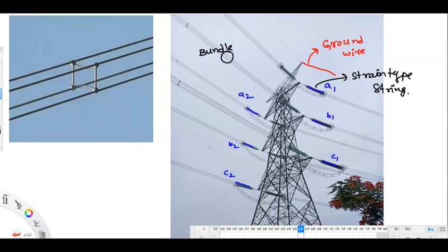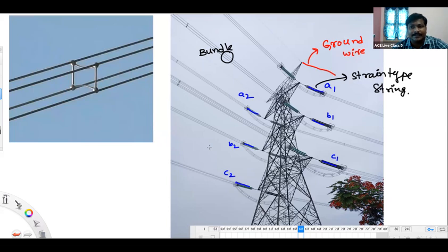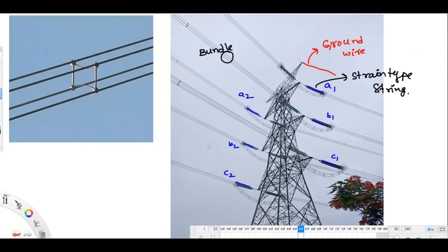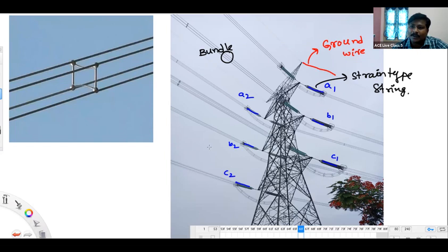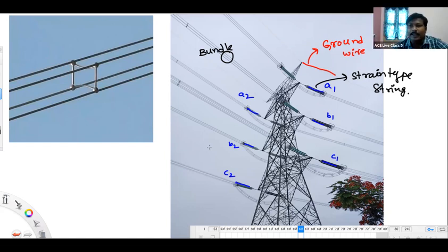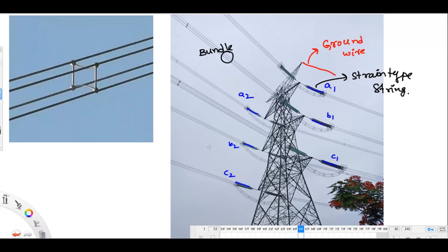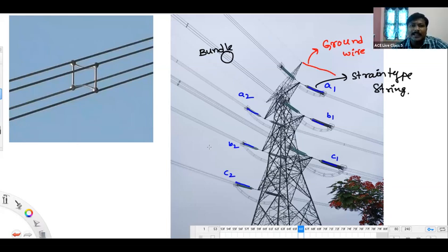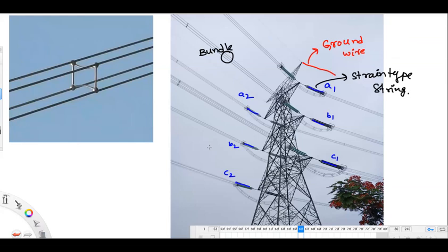After adding the internal term to the external, you will get r1 dash. If you don't have it, you have to consider only external, which means it may be only r1. What is the external inductance formula? Mu 0 by 2 pi ln of d by r1 dash is the total inductance, not external; internal plus external is that formula. For external: mu 0 mu r by 2 pi ln of (d minus r2) by r1. D minus r2 is approximated to d, so d by r1. That's it.